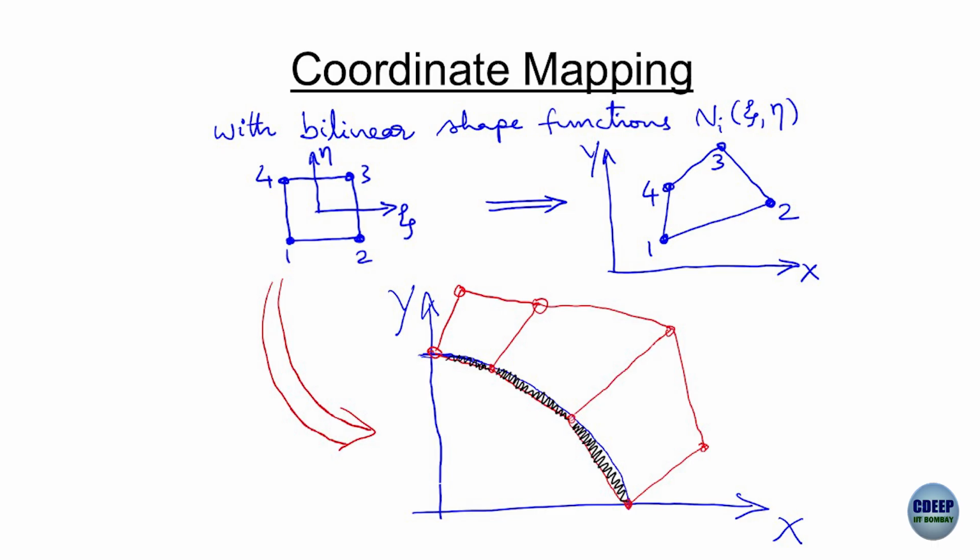Refine the mesh. Refine the mesh. So, you have 2 options, H refinement and P refinement. So, I can, instead of 3, I can take 300,000 elements. So, each will be a tiny straight line like that. So, the extra material I have added will become less and less, but can never be 0.